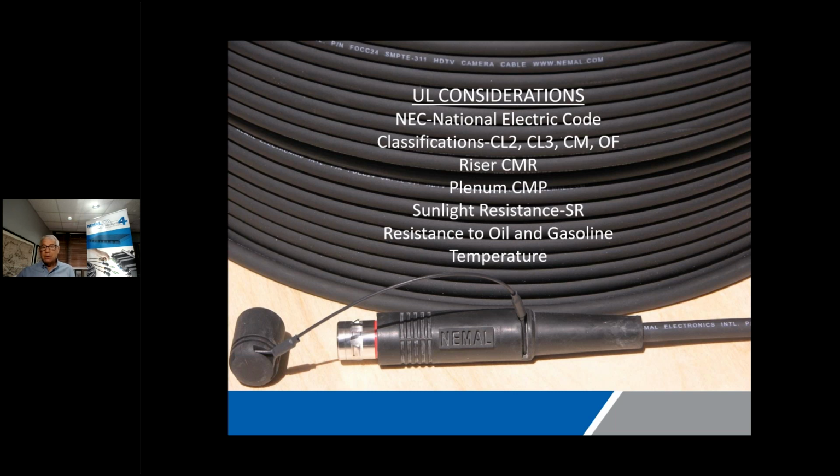To meet a plenum specification, you have to use specific materials which are drastically different in size, flexibility, weight, and cost than materials that we use for other ratings. It is extremely important that in any new facility or even changing out cables in an existing facility that you are aware of what the requirements are in your jurisdiction, because we have heard many stories of people not taking the time to do that, spending a huge amount of money and many, many feet of cable and having an inspector show up and say, take it out, and you have to.